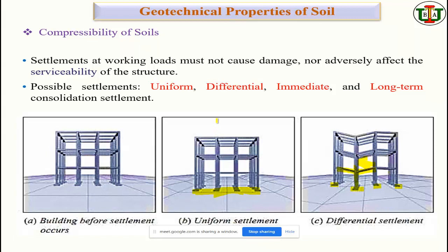When you design this one, you will take only vertical. But due to the settlement, it is having horizontal or lateral force. So the load transformation or load transferring mechanism has been changed due to the partial settlement. So that is a dangerous point for the structural integrity. Is that clear now?